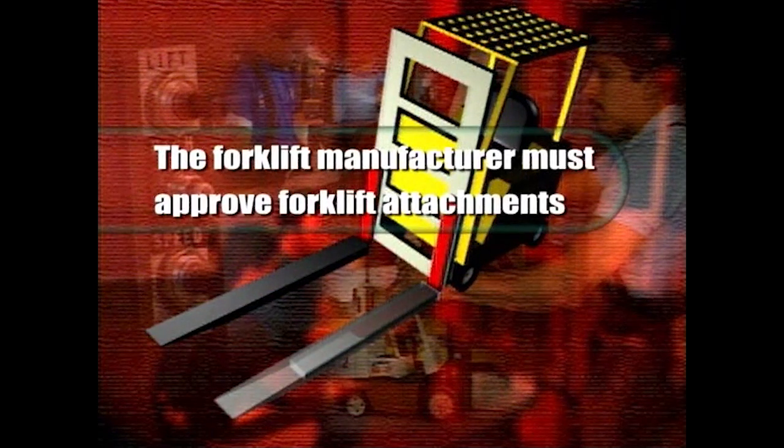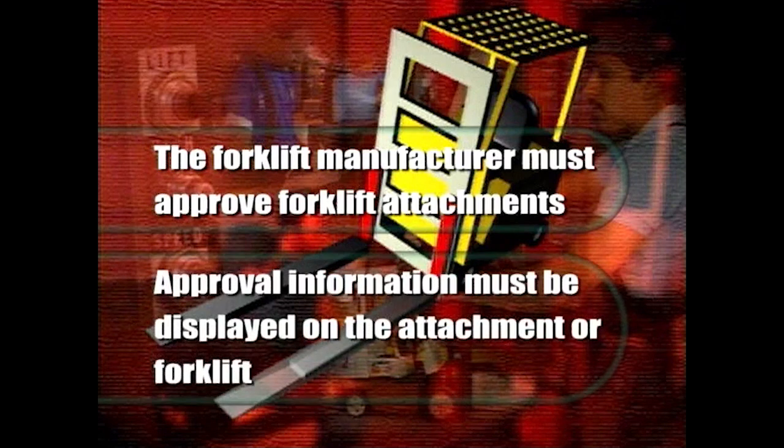The forklift manufacturer must approve forklift attachments. This approval information must be displayed on the attachment or forklift for the attachment to be legally used on each specific forklift.